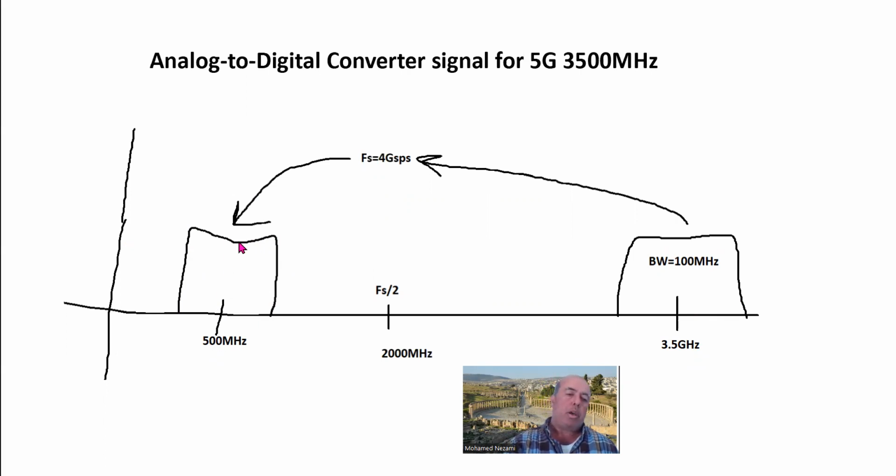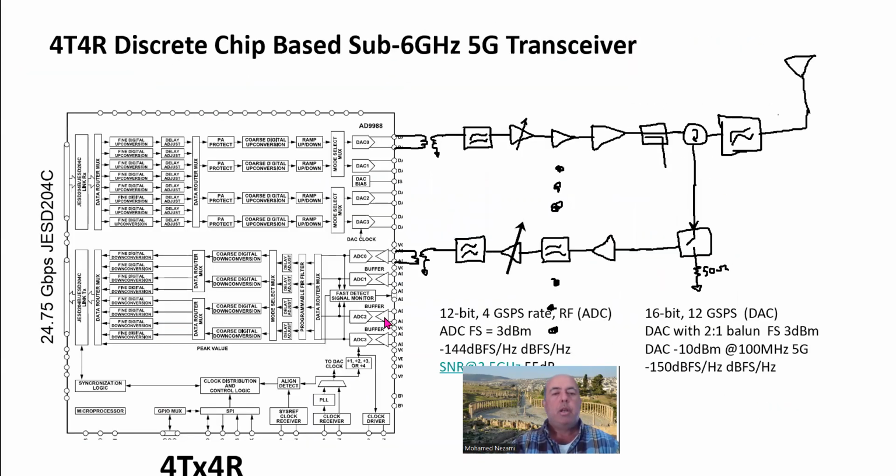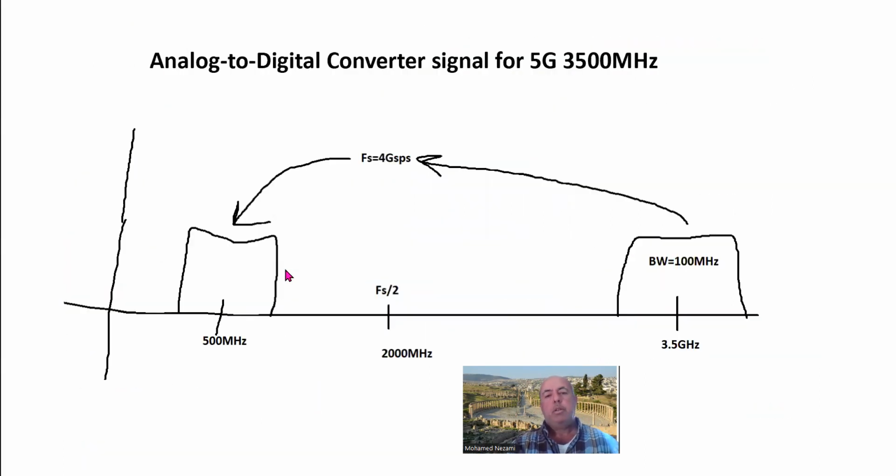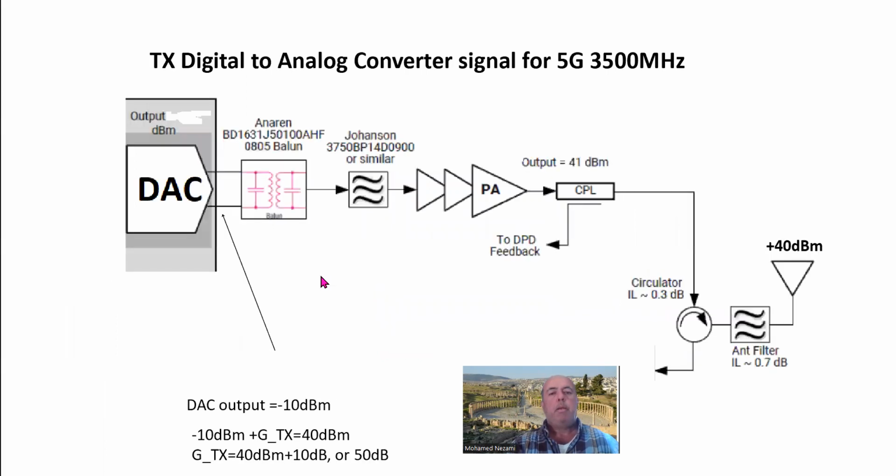So then you would have to rotate it to baseband to do the decoding and other signal processing, and that can be done with numerically controlled oscillators basically. And these functions are available for you in this path here. So you've got the down conversion digitally here and stages of that, and then you have various other tools as well, okay?